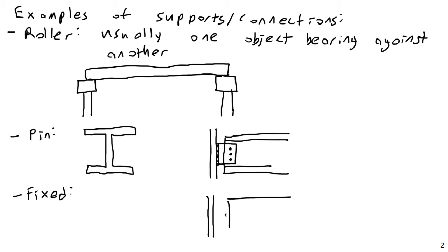But that's not always the case. There may be some edge cases, detailed finite element models, or maybe some more complex seismic analyses, where that might not be as conservative an assumption as you would think. But in most general civil engineering cases, it's conservative to assume a pin where you'd otherwise have a fixed joint.